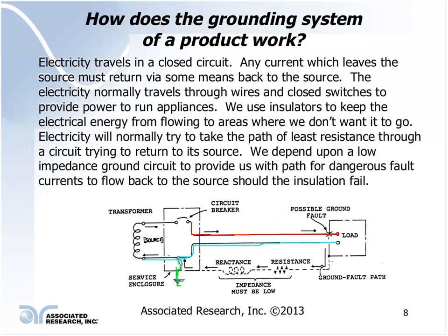Electricity is kind of the same way. In order to get that motor to initially start to turn, it requires a lot more current. Therefore, we have time delay fuses and circuit breakers. These are designed for a motor start application, where they allow more current to flow through the device for a short period of time to allow the motor to start to turn before the fuse or circuit breaker opens.